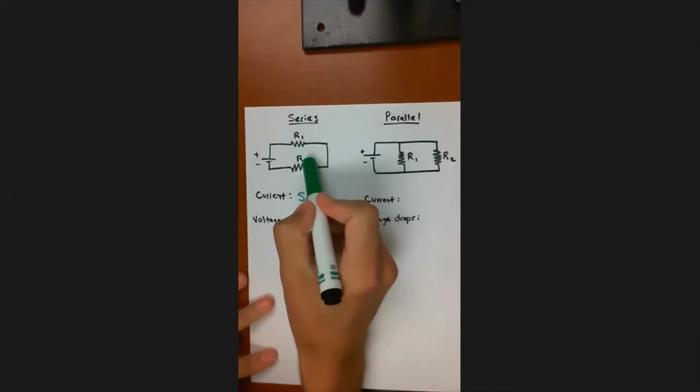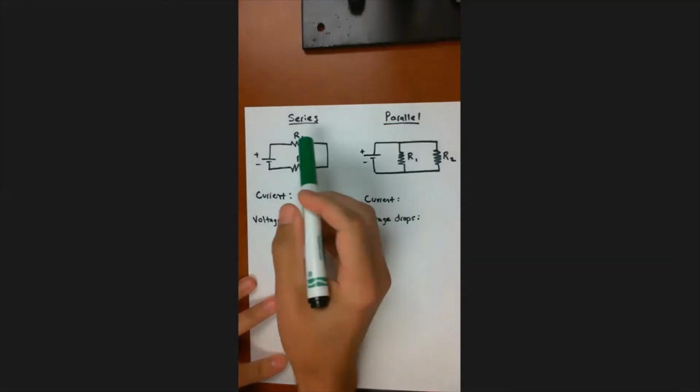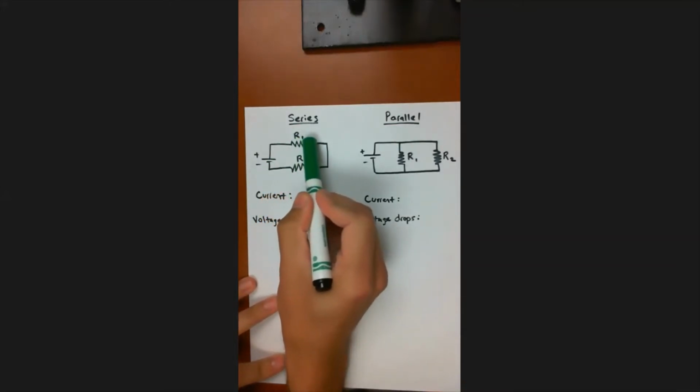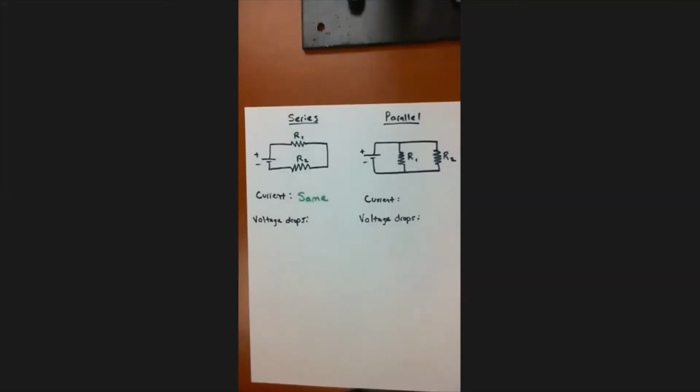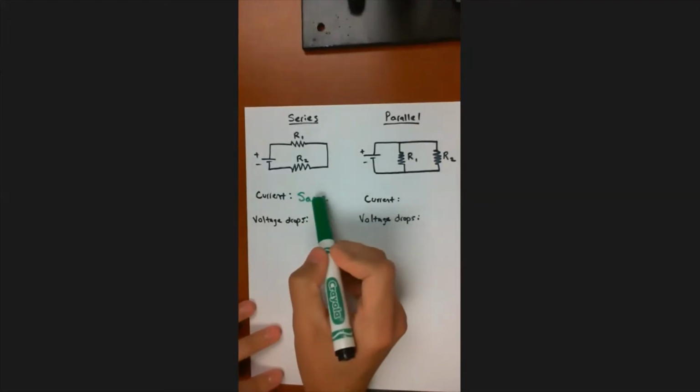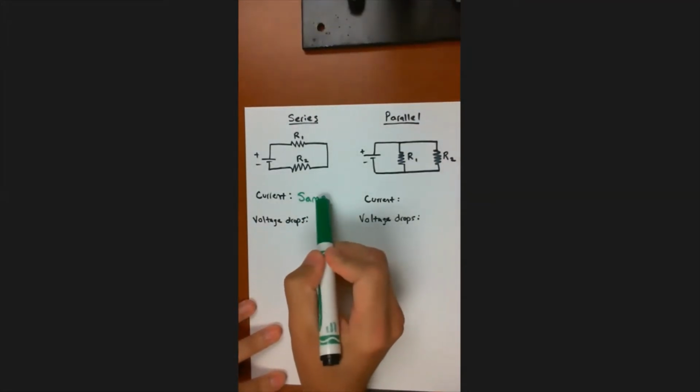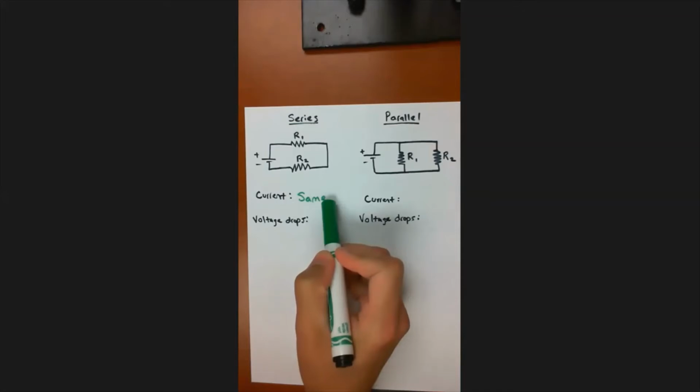Two components are in series if whatever current flows through one component has to also flow through the other component. That's a pretty good definition of a series circuit, actually. So the current flow through components that are wired in series is the same. It has to be.